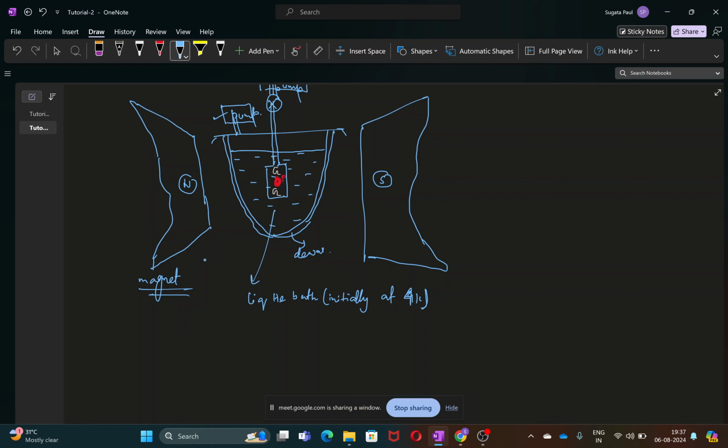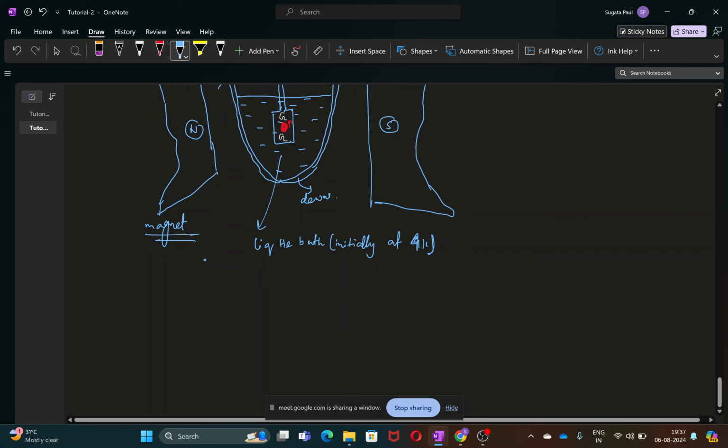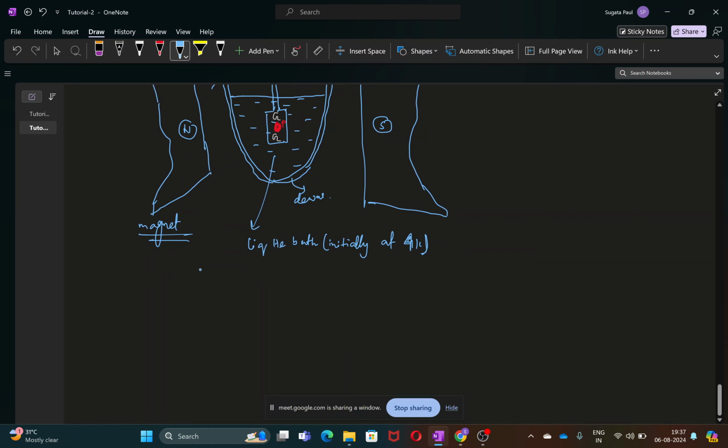The pump sucks out the helium vapor accumulated on the top surface of the helium bath, and because of this continuous pumping, the bath goes from 4 Kelvin, the natural liquid helium temperature, to around 1 Kelvin.